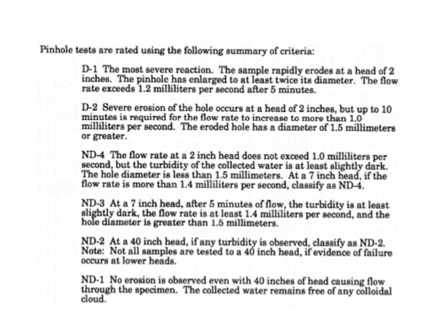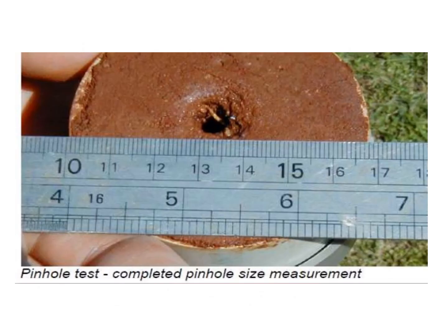The collected water remains free of any colloidal cloud. So in this way, we can classify the dispersive clays. So here you can see the completed pinhole size measurement. So this is the hole which is present in the dispersive soil.